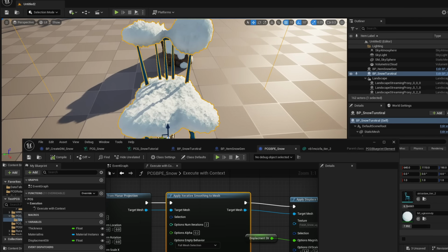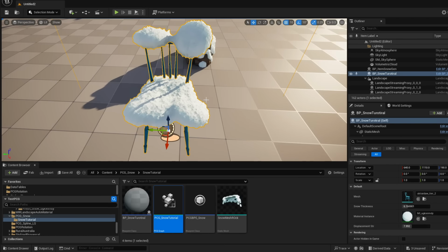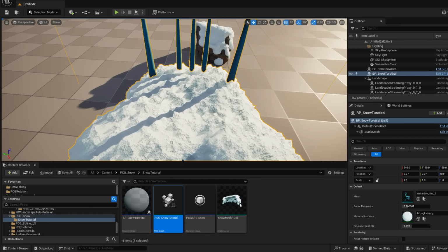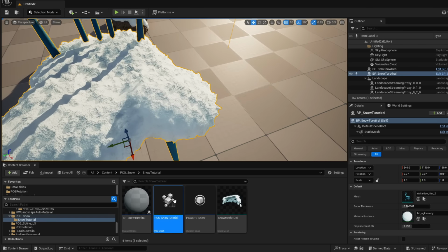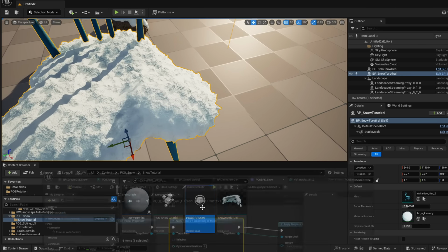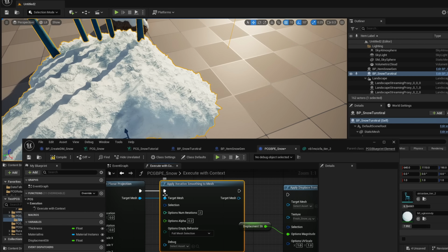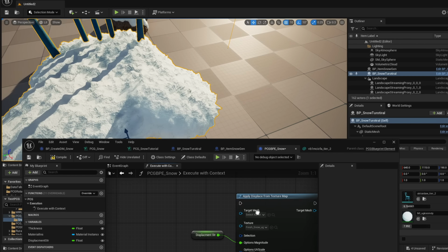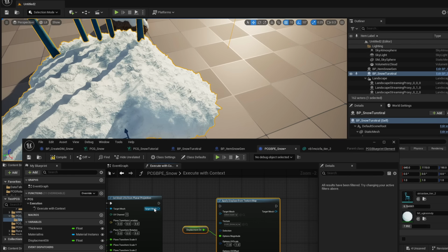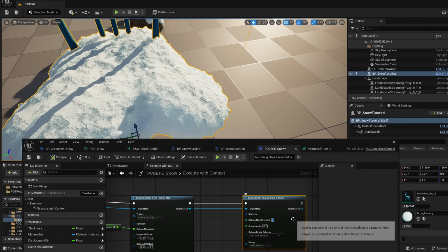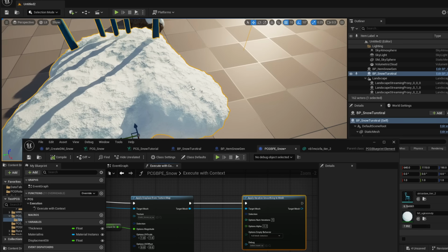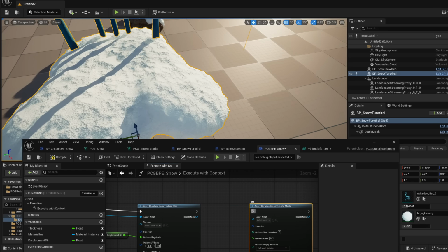This mesh is a little bit too round in order to see the difference of the smooth, but for example, let's do the smooth after the displacement so you can see the result a little bit better. I would not recommend this because it doesn't make sense to displace it and then smooth it, but I just want to show you that you can apply some different transforms here in this blueprint. So you can see now we are smoothing. Let's increase it to 5. Compile. It's even smoother.